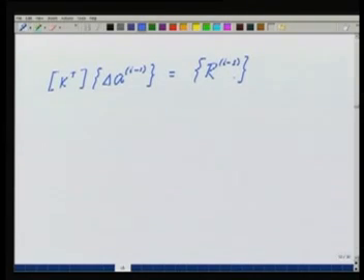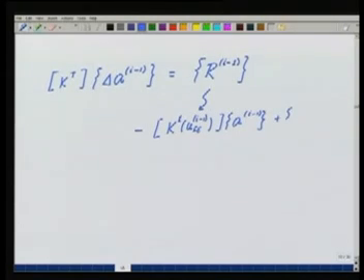Okay, what is R at the step i−1? It is obtained by putting U_FE at the step i−1 in the expression for the stiffness matrix and the load. Okay, so this will be K due to U_FE at the step i−1 into A_{i−1}, minus of this plus F at the step i−1.